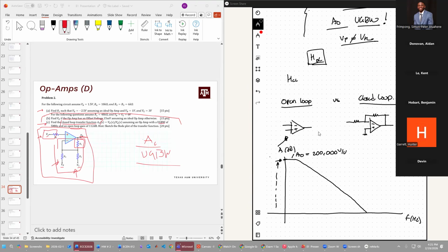When we're talking about op amps, all this graph is telling us is that the higher the frequency, it's just comparing the gain versus frequency and the relationship that we're seeing. So if you're building a device and you want a gain of say 20 volts per volt, right? You would go to the portion of the graph that's 20 volts per volt, and then you'd see this response. You're going to draw a flat line all the way up to the open loop response. And just to make it a little more clear, let's give it a different color. Let's call this graph red here. And then we'll continue from the open loop graph like this, right?